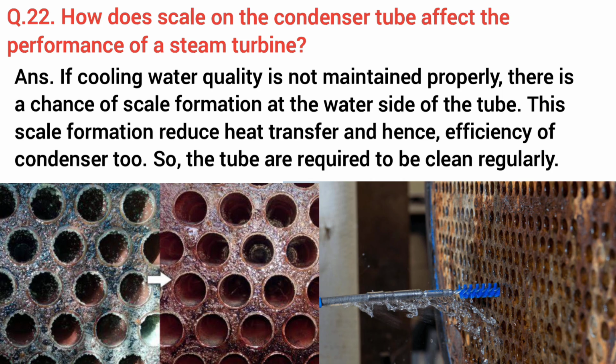If cooling water quality is not maintained properly, there is a chance of scale formation at the water side of the tube. This scale formation reduces heat transfer and hence the efficiency of the condenser. So, the tubes are required to be cleaned regularly.